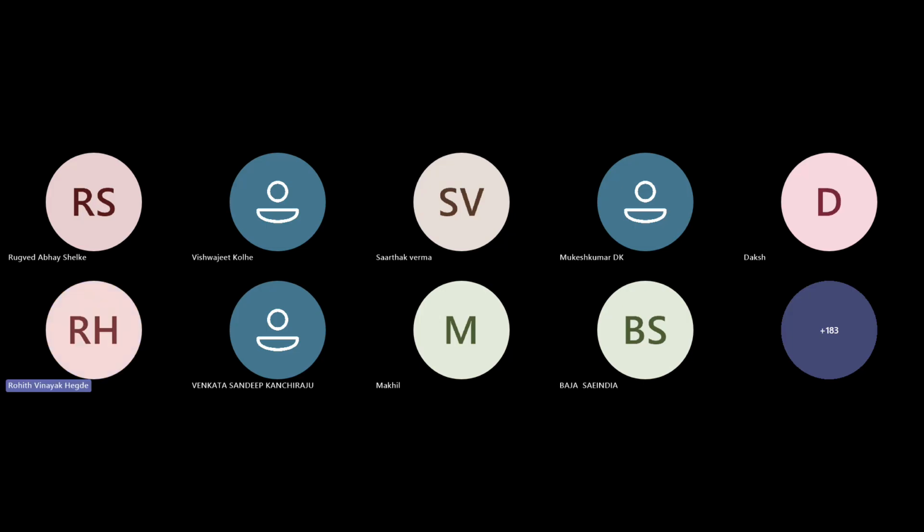While they're building a project folder, they have to just select the SRC source build environment. It will create SRC files and they can import that file inside MATLAB. Then there is one script, cm, that they have to run in the terminal. Then there is something called the generic model. From there, they can start creating their own models, maybe brake or other models.